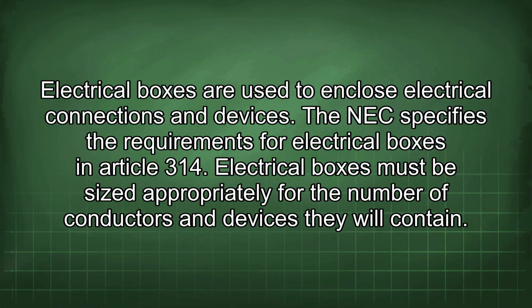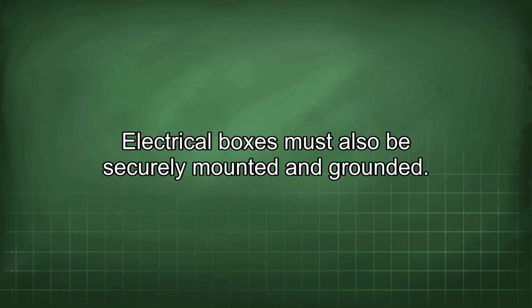Electrical boxes are used to enclose electrical connections and devices. The NEC specifies the requirements for electrical boxes in Article 314. Electrical boxes must be sized appropriately for the number of conductors and devices they will contain. Electrical boxes must also be securely mounted and grounded.